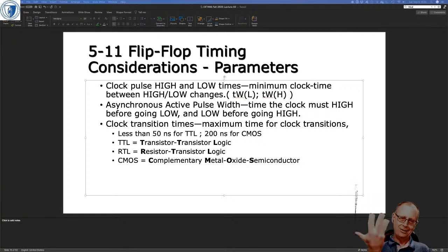Unfortunately, your hand and that act of walking, now I don't know whether the lab has had some anti-static measures taken, so it's probably not as bad as this, but simply touching the leads, the legs on those devices can induce static damage.